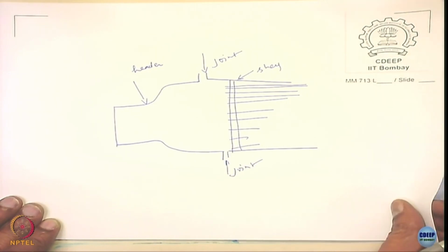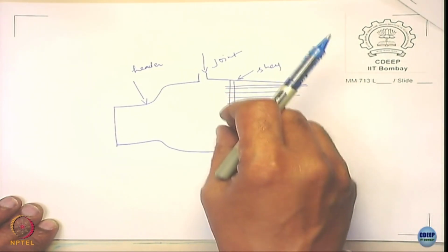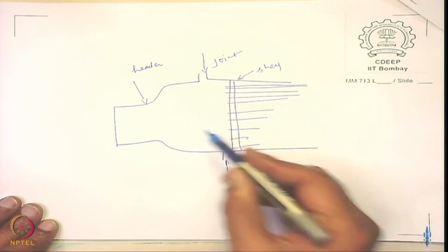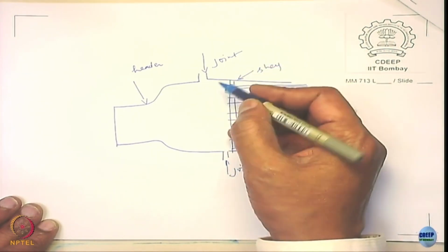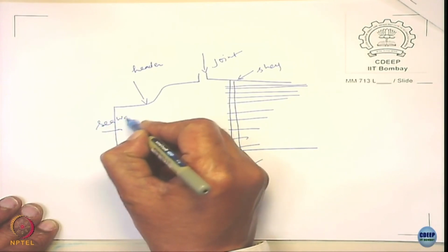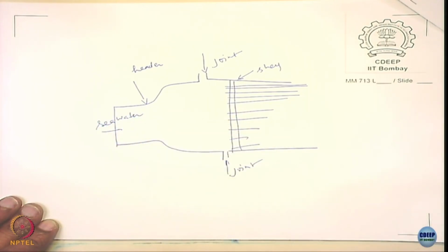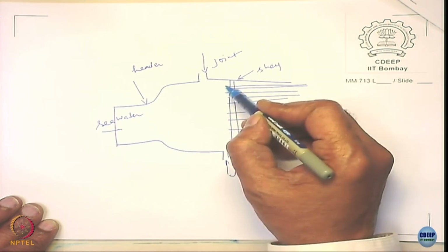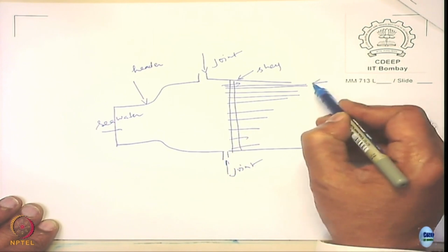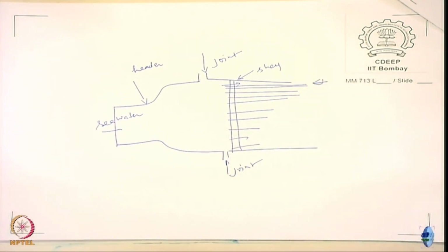okay. So it is a header that has suffered the corrosion, and through this you have seawater, right. Now the seawater here is flowing through the shell side, the tube may be some other process liquid, it may be some hydrocarbon or whatever that flows into that actually, okay.